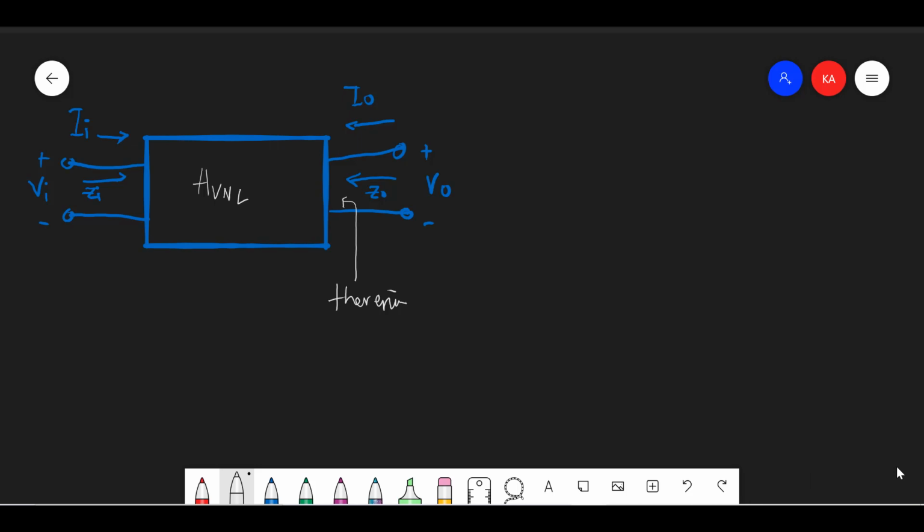So it is very easy for us if we look at each single amplifier as a two-port system. So we have 3 amplifiers, so we have 3 two-port systems, and then for cascade we only have to multiply the gain of each two-port system to get the total gain of the amplifier.